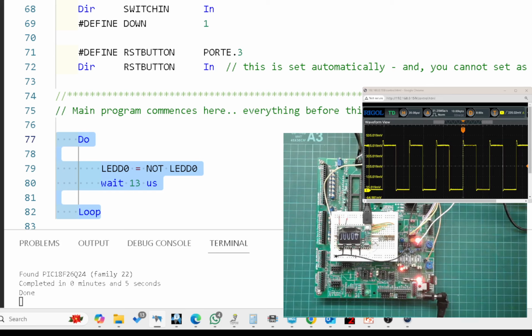But to be quite frank, it's what's called blocking. If you go and do something else in the code, it doesn't work. So it's a way of generating a signal, a valid signal. And you could do a repeat around this in terms of a repeat loop. And you could send out a number of signals this way. It's a method. It's pulse width modulation.